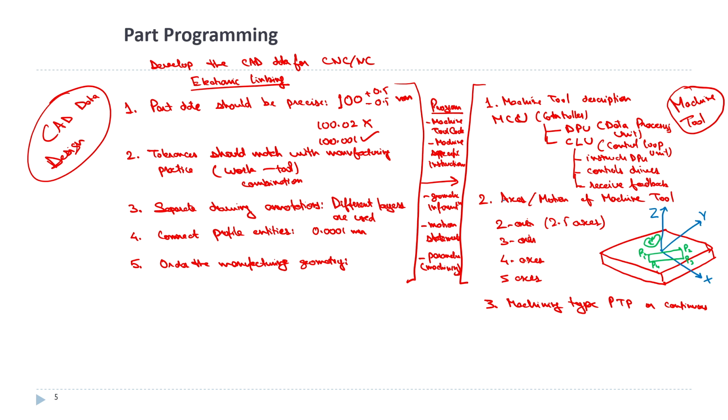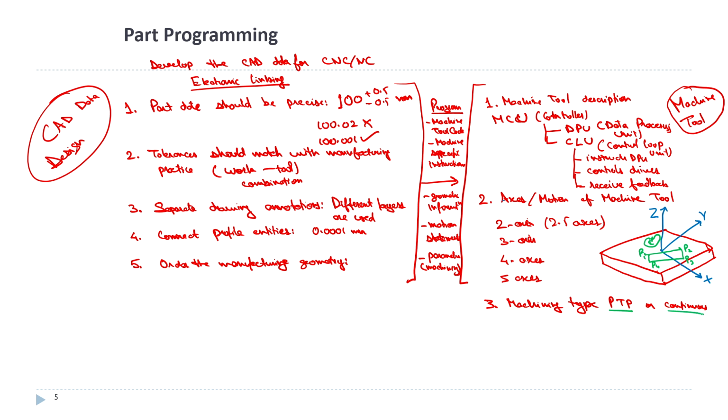All these things are taken into account when we write a G code, when we try to develop the decision support systems. The machine nowadays understands by itself, the systems are automated, but we need to understand whether we are working with a 2-axis machine or a 3-axis machine. If it is a simple drilling machine, point to point is the only type of machining that it takes. The exact path of the tool is followed by moving from point to point, regardless of the time it takes.